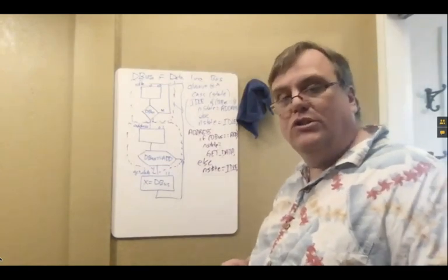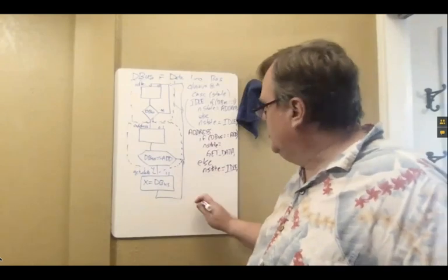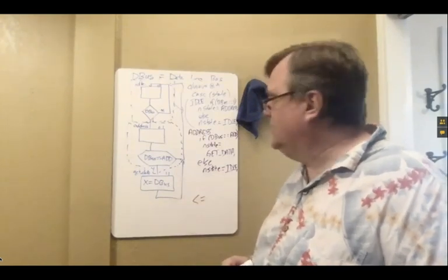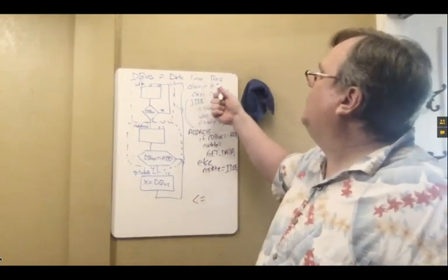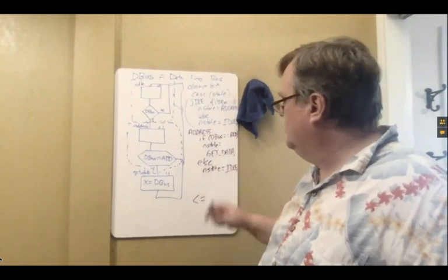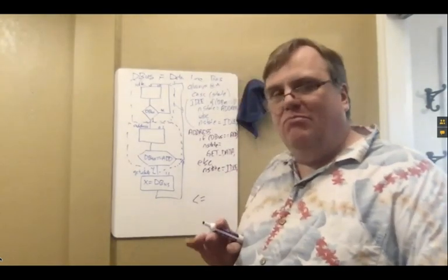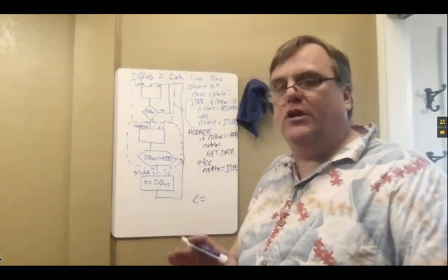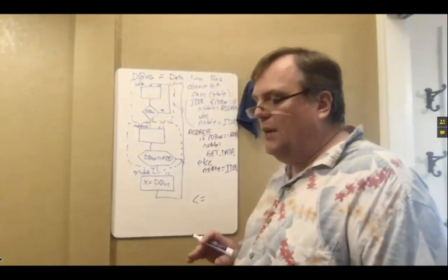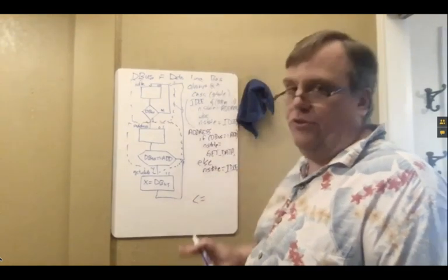All right? And again, I use my names all the way through. Now, if you noticed, when I was doing the flip-flop, I was using my non-blocking assignment. Inside my combinational one, I'm using blocking. It's just a safer convention. There is a couple cases that you can run into problems if you don't follow this convention.